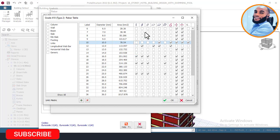Now for my wall reinforcement, BS code specifies that the minimum bar size to be used is 10 basically, but me, I don't like using 10 because 10 diameter bars, I use them for links. So I go ahead and choose 12 as my minimum bar size for my reinforced concrete walls, and I also choose 16, 20, 25.